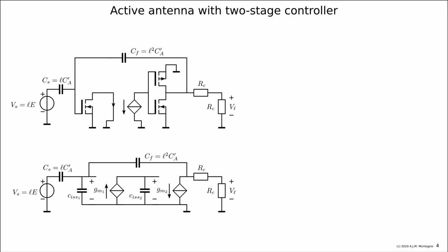So if the feedback capacitor is smaller than both the input and the load capacitance, then of course, it cannot introduce a new pole because it would be a loop of capacitors, but also its influence on the product of the poles is negligible. Only it affects the sum of the poles, which is described by the Miller effect, which means that if I would now evaluate the poles and zeros of this circuit and compare it with the result, for example, obtained from SLICAP, in which those capacitors are present, then I would find a different result for the sum of the poles, but not for the product of the poles.